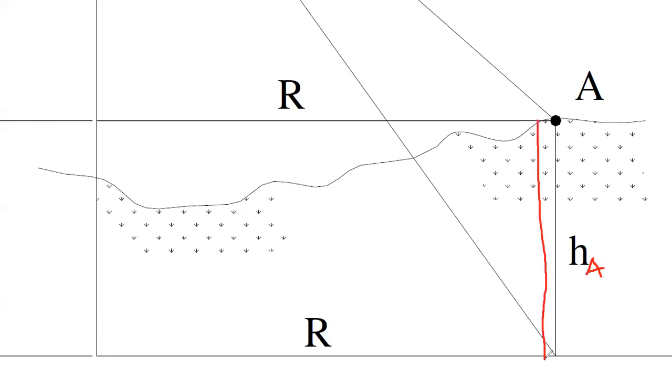From here to here is what is making us talk about relief. Are you okay? So an area without relief is an area in which the ground is almost flat. Okay, then there will be no relief. In other words, the datum can be assumed to coincide with the ground surface.